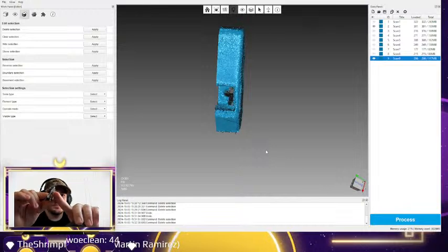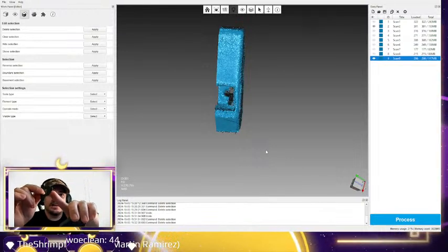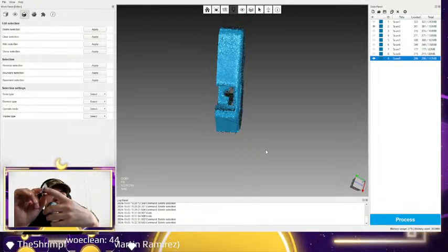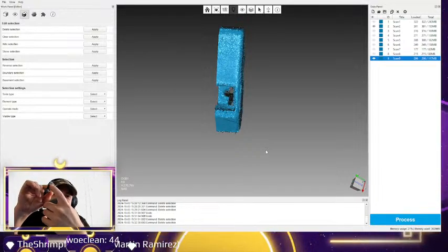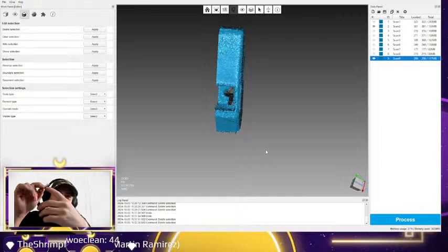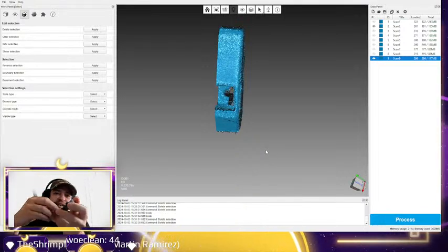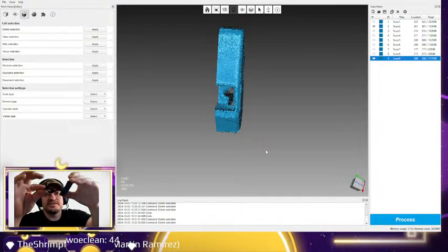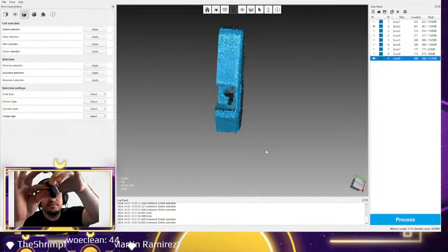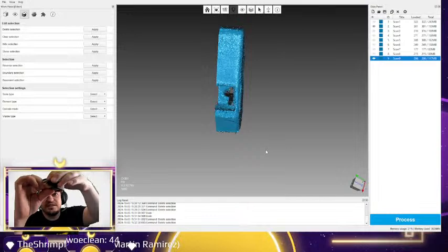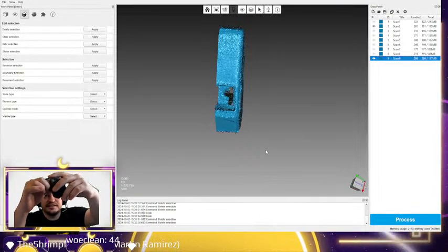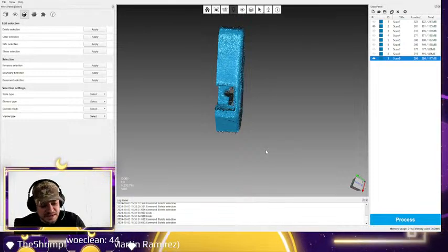I'm going to make this part a little thicker, and it's almost going to be like a letter I, right? It's going to have a flat, long piece of TPU rubber filament that's going to extend out, and then that other end of the I is going to be here. So it's going to lock in there and give it that rubber elasticity, so then you can clip it closed in its little area. So we're going to be scanning and modeling that.